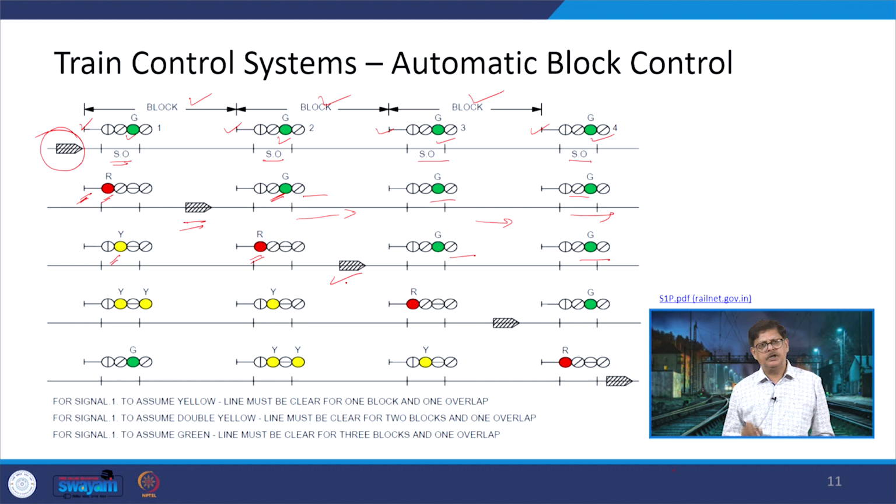So, that means this train keeps continuously moving, and now it comes into the third block section, and as soon as it comes into the third block section, the entry point stop signal turns into red. The previous stop signal turns into yellow as compared to the red which was there previously, and the previous signal, that is this one, turns to double yellow. When it turns to double yellow, that means a distant signal is there. So, there is a cautious condition, more restricted, you can move in, but be ready to stop if the other signal gives you that indication. So, this is how the 4 aspect color coding system is working here.